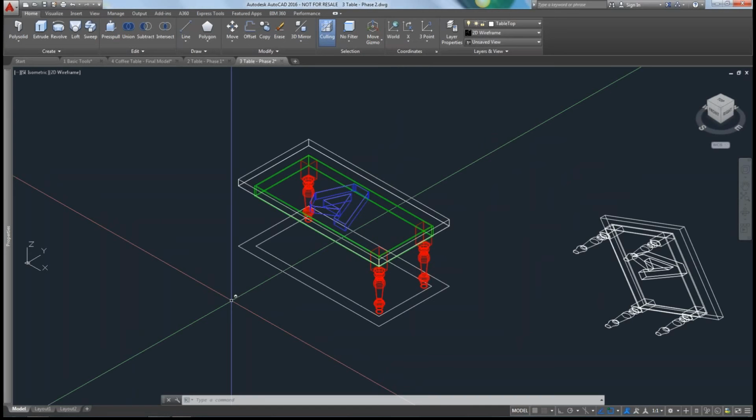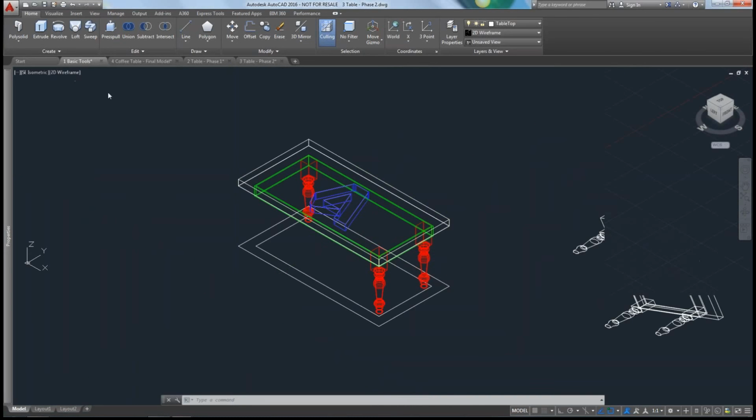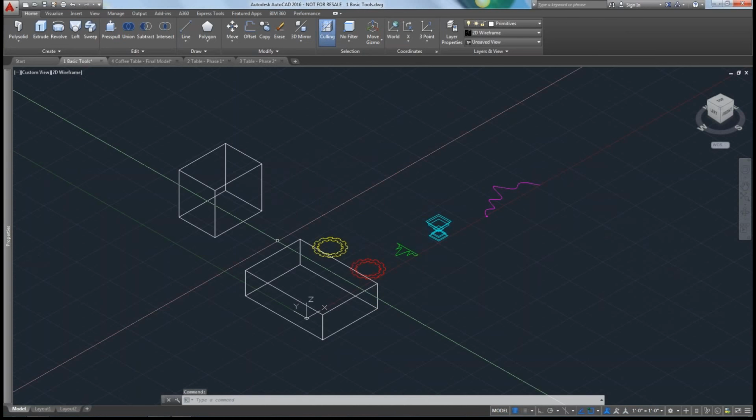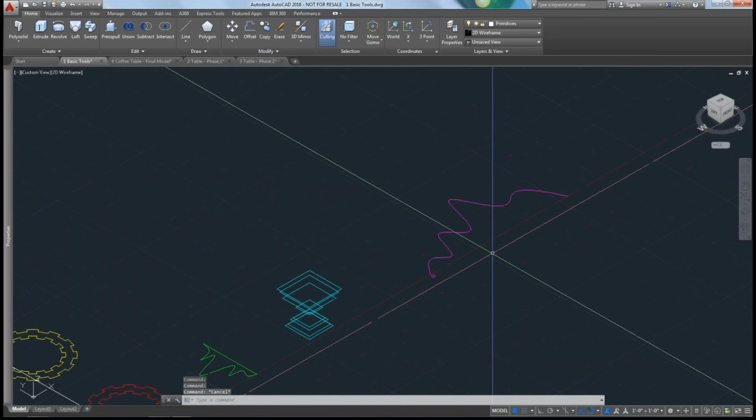you would want one continuous path that you can see here. For instance, let's say that was your path. The problem is that the 3D polyline, which can draw a polyline in the X, Y, and Z axes, cannot support curves.